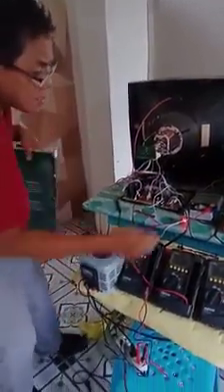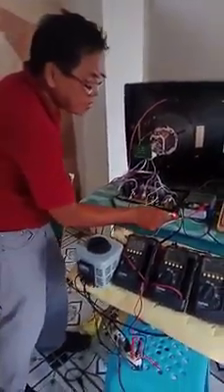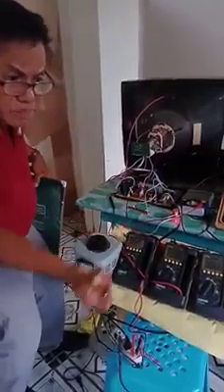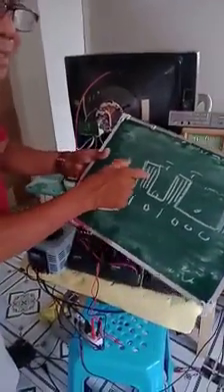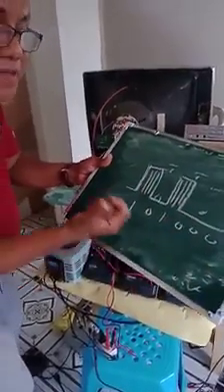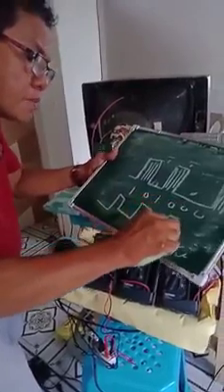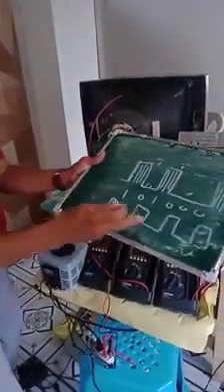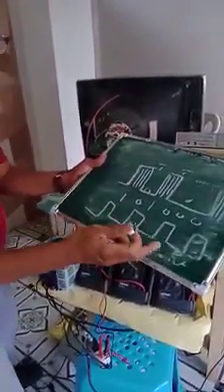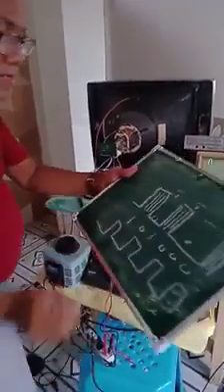But as it is received by the infrared sensor and submitted to the MPU circuit, this 38 kHz is demodulated and filtered out. What comes out and is fed to the microprocessor unit are the pulses only, containing the binary information. For example, volume up, volume down, channel up, channel down, different pulses.